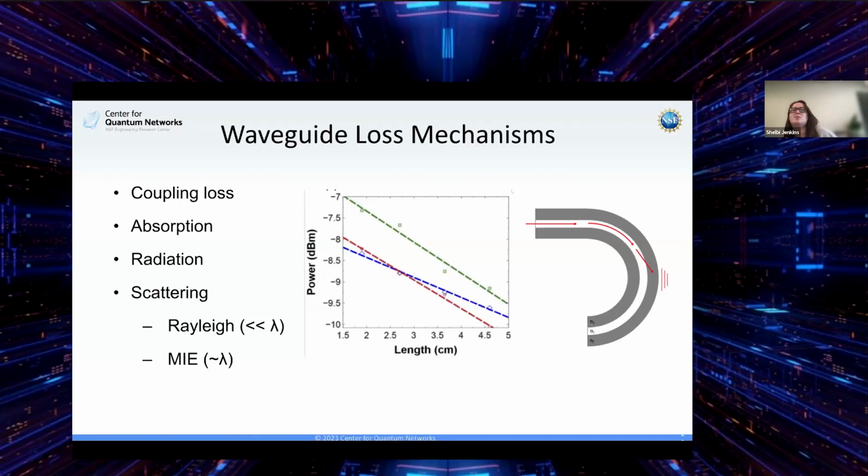That's also true if you're just working with fibers. When we talked about our network with our WSSs, where there's 4 to 8 dB loss, a lot of that is going to be coupling loss. It's generally a very inefficient process, especially if you want to do switching where you have to move between different waveguides. There are ways to minimize coupling loss, like index matching fluid. That's one option, but generally it's just accepted that you're going to see some loss, typically on the order of 3 to 6 dB for coupling.